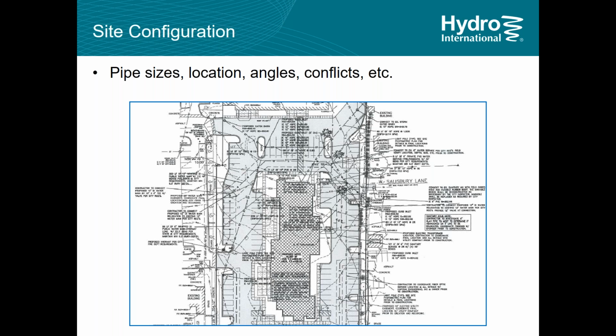Often, it's actually more effective to put 2 or 3 smaller systems around a site than trying to bring everything down to one end of pipe system. When you start making these things bigger, costs escalate, cost of installation escalates, and costs of maintenance escalate, and having 2 smaller systems located throughout the site is often more efficient in terms of a long-term ownership cost than one big system downstream. So these are the things that need to be considered as well when you're looking at separator or treatment design.